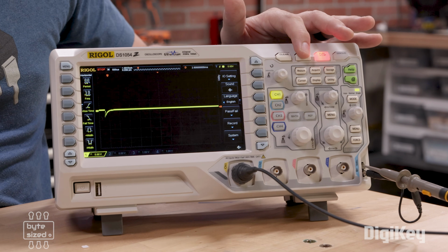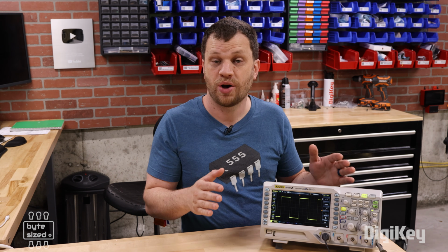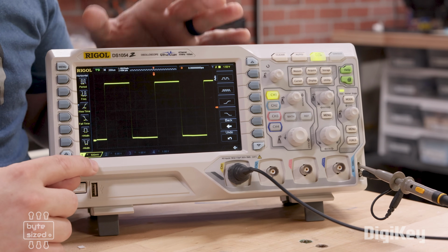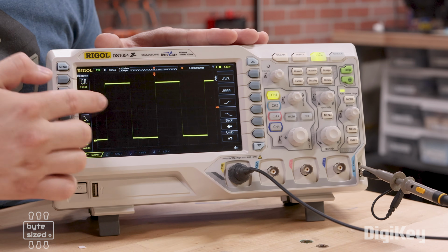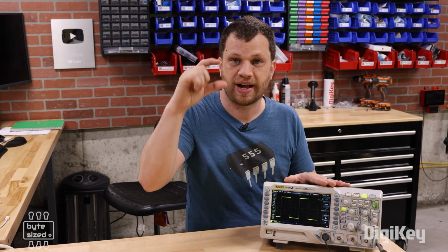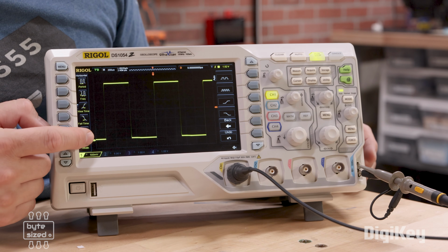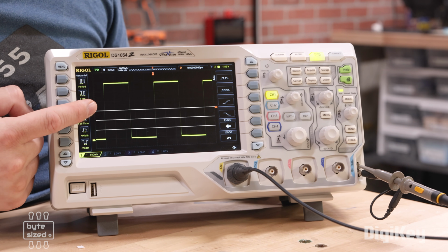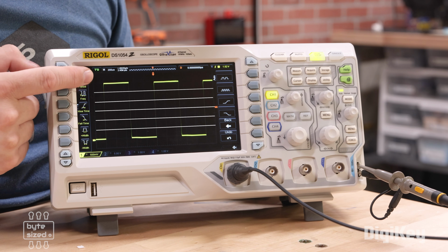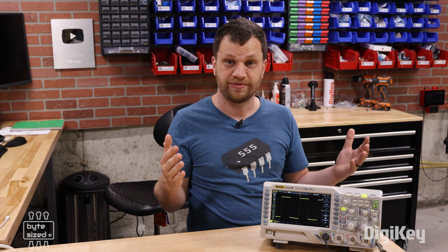The simplest way to start measuring on an oscilloscope is to hit the auto button. This automatically adjusts both the vertical and the horizontal scale. So let's see how the scope adjusted for this signal. If I look down here, I can see that my vertical resolution is 500 millivolts per division. That just means that every horizontal grid line going across the screen is 500 millivolts. So I'm going to look for the ground reference down here, and I'll count the divisions and see what voltage this square wave is. So we have 500, 1000, 1500, 2000, 2500, and 3000 millivolts. So that is a 3-volt square wave.